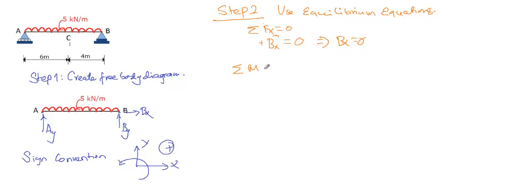The next step is to calculate moment about the beam support. Usually we take moment about beam support. So AY is the reaction times distance 10 meter, and it will rotate the beam in clockwise direction, which is opposite to our sign convention, our assumption, so this is negative.